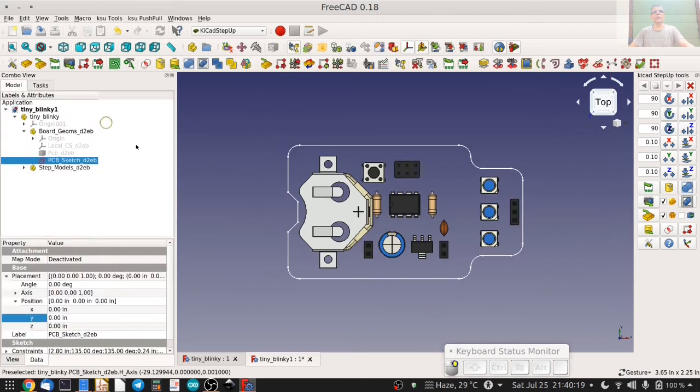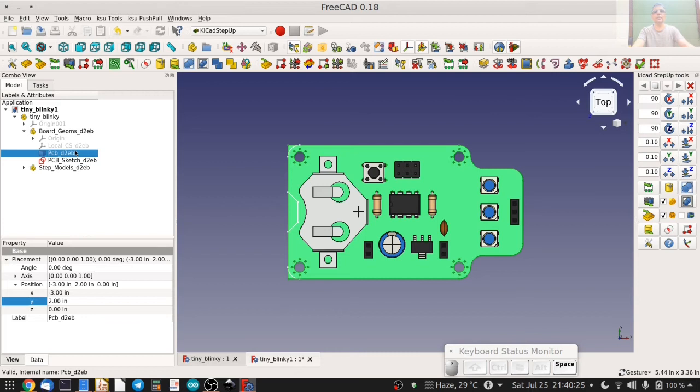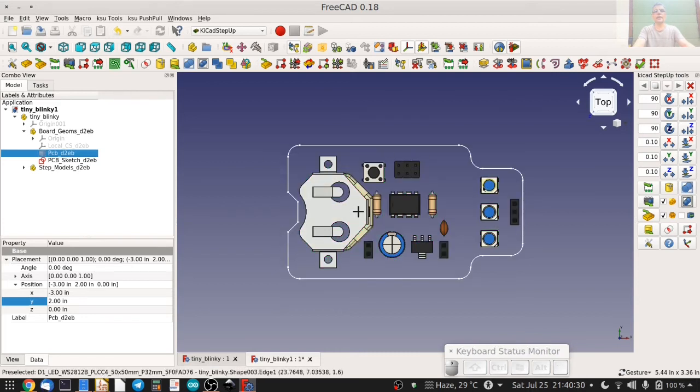So let's close this, and this is our revised outline, and this is the original PCB. So we want to change this PCB into this outline. The way you do it, once you have got all of this done in SketchUp, you select this icon which says push sketch to PCB edge. If your toolbar locations are a bit different, you might have to look around for it. Push sketch to PCB. Choose that.